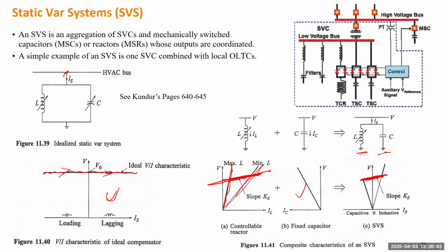But this system has a drawback. If you can make sure to operate within this operating area, that can guarantee the voltage to be controlled around the setting point. But what if you reach the limit? You are going to follow this line or this line to move. That will suddenly change the voltage.